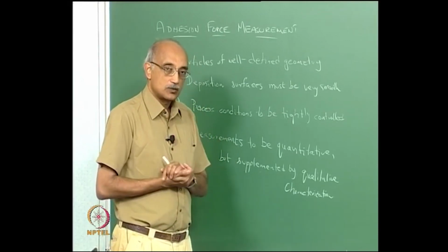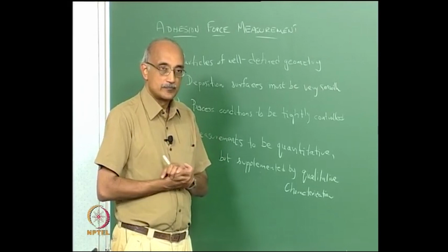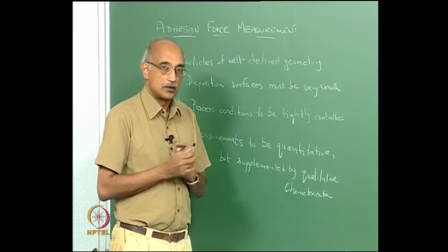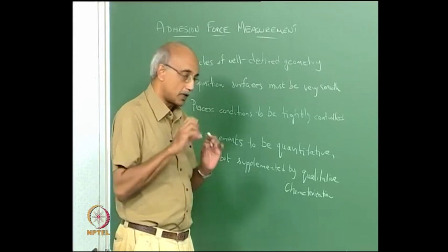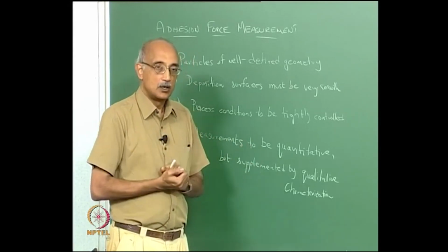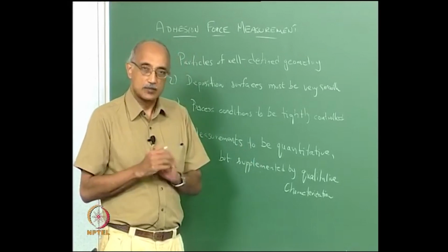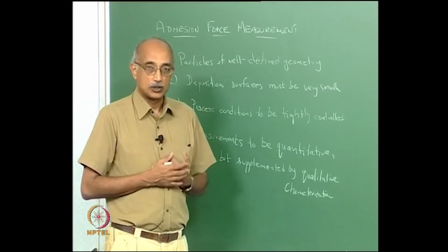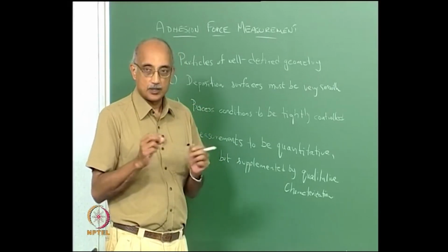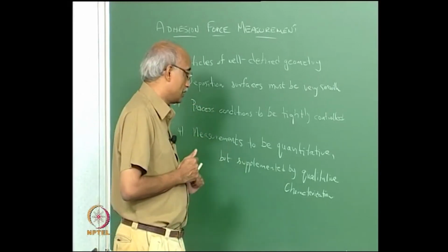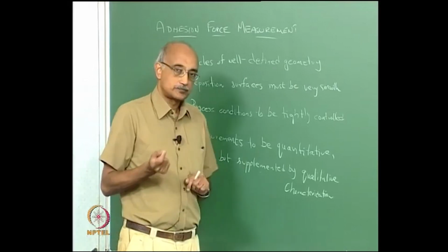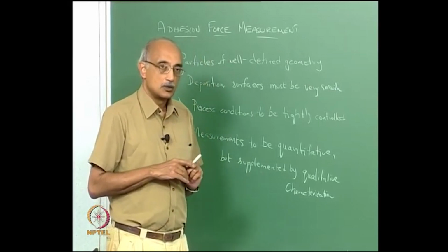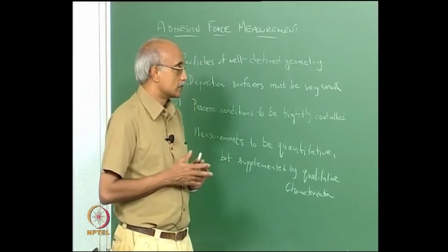Make sure that what you are counting as a particle is really a particle and not just a feature of the surface or material that is part of the surface which has broken off, or a simple hole in the surface, because all of these can fool a particle size analyzer or even a particle counter into thinking that these are particles. So it is very important to be open to doing auxiliary measurements that can confirm your quantitative data.